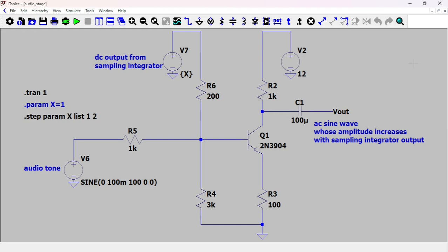And then as you come closer to the metal target, the pitch increases, in other words, the frequency increases. And as you get away from the target, that frequency decreases, and the pitch gets lower. So that's called VCO, and that's another way to do it.